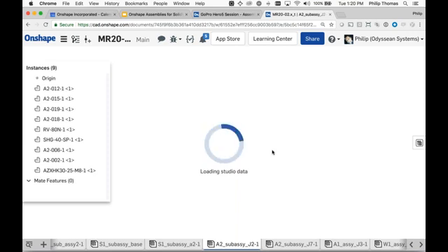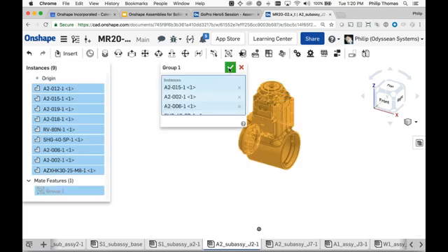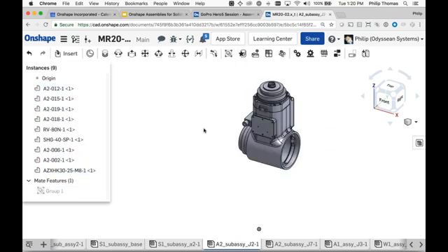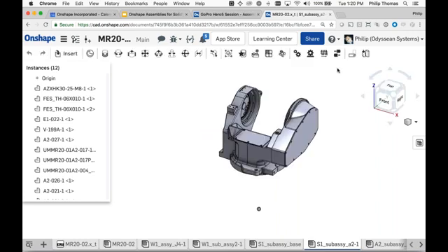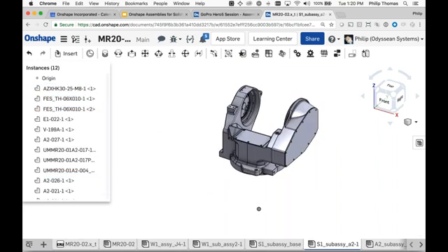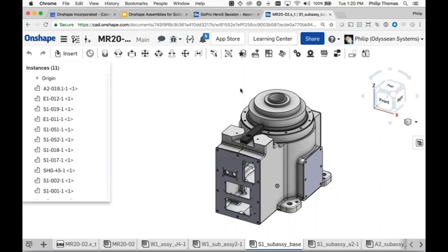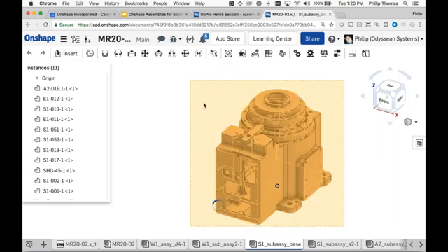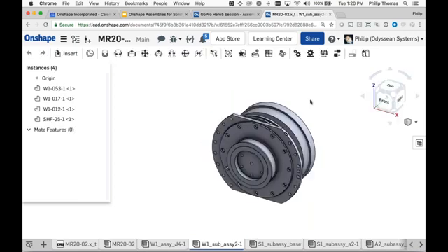The obvious benefit that people assume exists is that by fixing a part, I keep it on the origin and that I'm somehow going to use the origin in a higher level assembly. This is not the case. Remember, all sub-assemblies are flexible. The part is not going to move off the origin in the sub-assembly, but can, because the origins don't appear in the parent assemblies, it's actually completely irrelevant, the location of the parts relative to the origin, so there's actually no need to fix one of the parts relative to the origin.